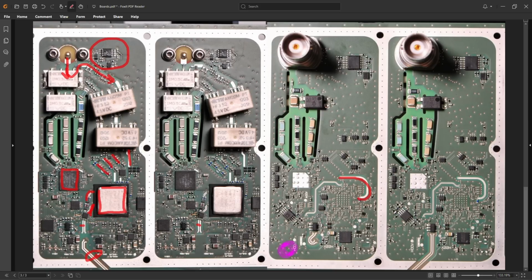So there's a little tiny wiggle of the PCB traces over here, completely unnecessarily, because they could just go straight, obviously. But they're not doing that because they want to make sure the same number of vias shows up on all the channels, because this one does have to go through the board because it comes out on the other side. So there are little subtle differences in the layout between them just to compensate things.